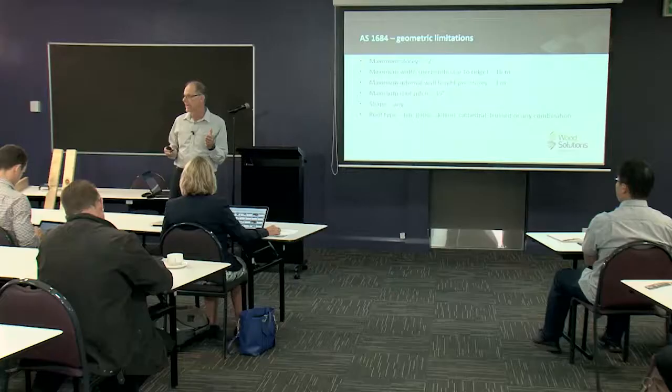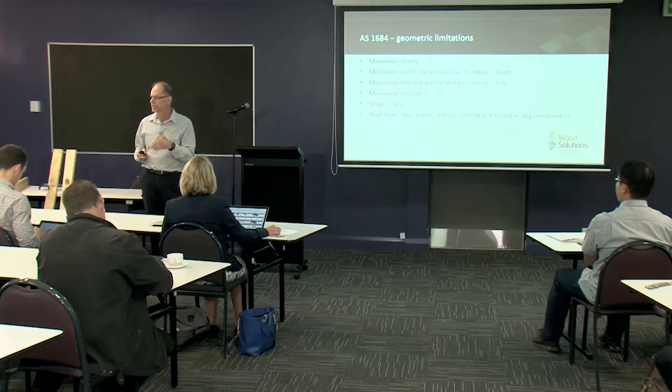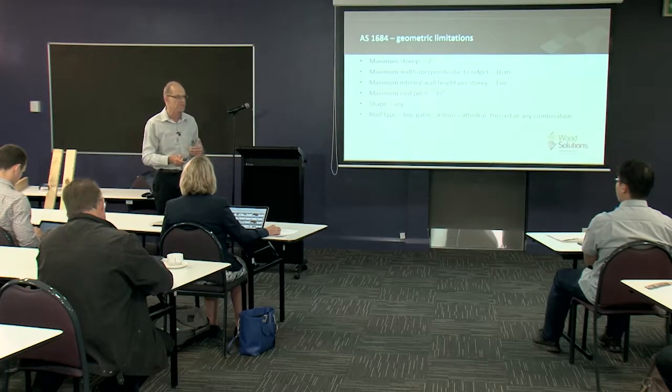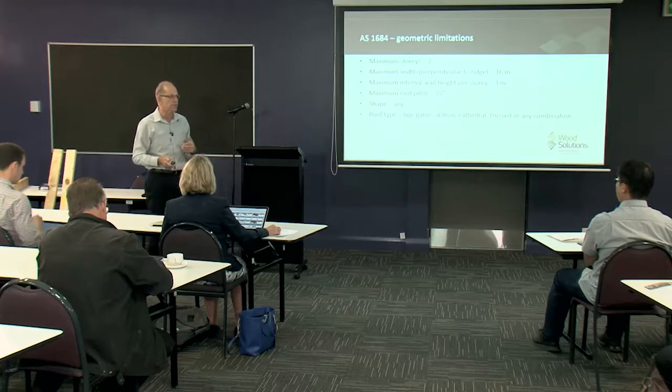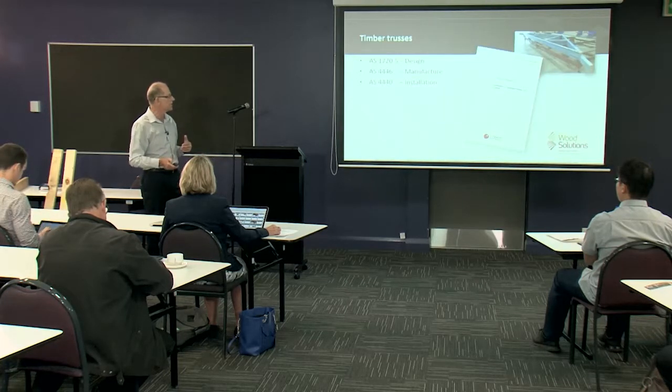If your building exceeds those limitations, if your house exceeds those limitations, AS NZS 1170 Part 2 is used for the wind loads, and AS 1720 Part 1 is used for the timber design.